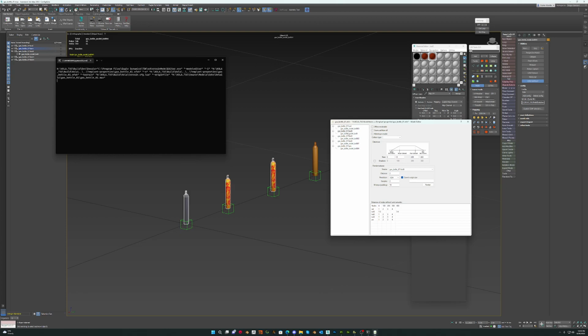Okay, so now we'll go down to the gas bottle LOD 0 model. This should be set to V-Ray House 5.1, which if you look down your list, it should be there. The semantic is building, no proxy bias. The flare type is building, and we want to use normal map for a LOD 0 item, so you can see the normals within the texture.